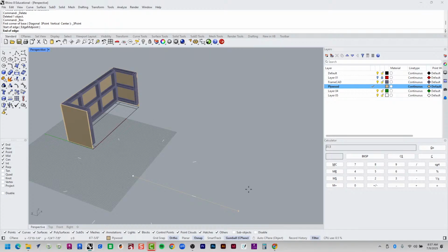I'd say like a half inch to an inch. An inch? So in the front side, overhang 1 inch? Yeah. Okay. So we know that the current overall depth of our cash wrap is 24 inches. So if the top overhangs 1 inch, it would be 25 inches. So end of edge, 25, enter.